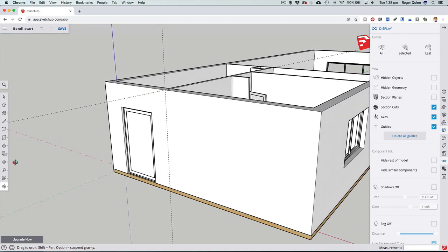Now I did that so that I can work out the width there, which is 4060 millimeters, and I just want to get halfway because I want to put the window smack in the middle of that space. So I'm going to drag this second guide anywhere, type in 4060, then / and then 2, which means divide by 2. So 4060 divided by 2, and there's our middle point.